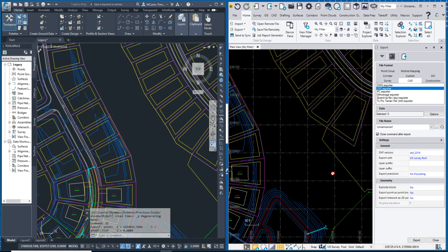When you're sending it out to our machines and our collectors, the project in SiteWorks, for example, is set up with US survey feet. So everything should work. Plus, you're also applying the calibration on a project, which would also affect it. Now, you want to make sure that you're working in US survey feet, and you export in US survey feet to the machine.